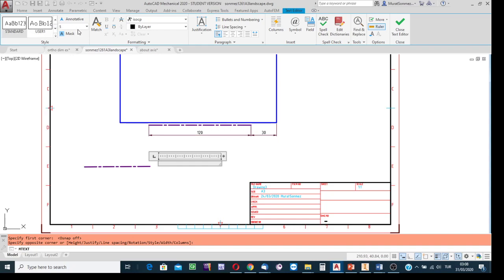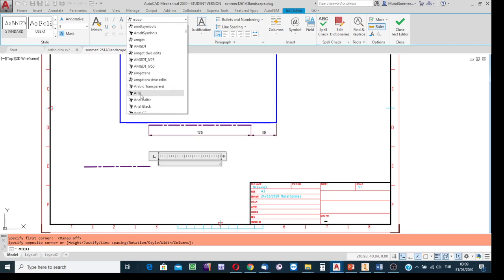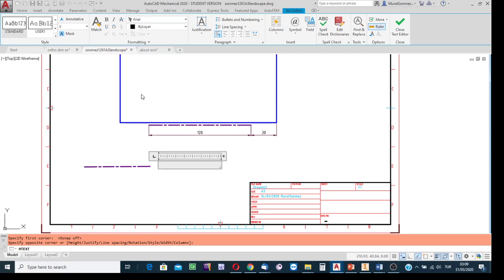It is just the font height, and then the font name. Later, I'm going to talk in a little more detail about lettering format and the text facilities of both software, but here this is just briefly to complete my exercise. I clicked on this listing arrow and from the list should select Arial as the font name. Scroll, it's a very long list, and select the Arial option.